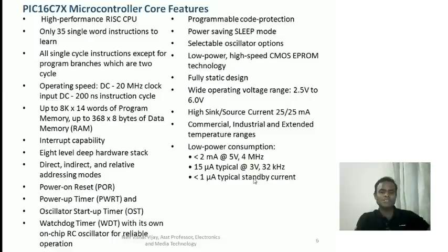The same way you have a sleep mode on your microcontroller, which can be set at your command. It has different types of oscillator options. As I said, you can select a low cost RC oscillator or a high cost but stable crystal oscillator also for your big microcontroller operations. And it can operate on low power. It can operate on a very wide operating voltage range from 2.5 volt to 6 volt.